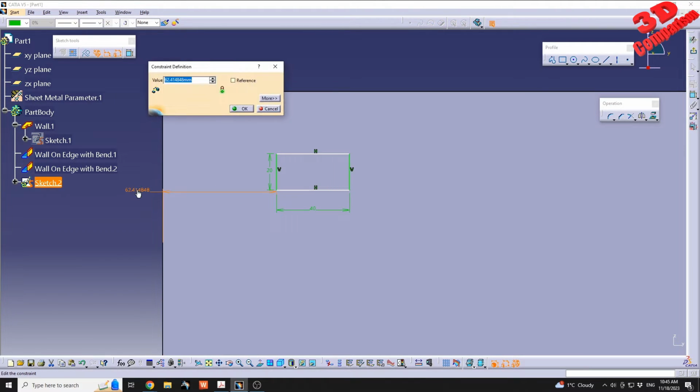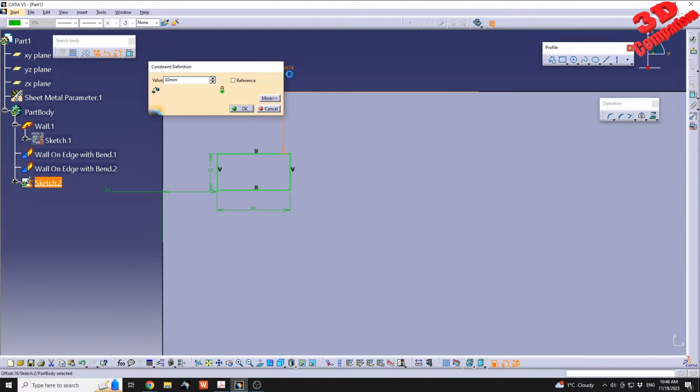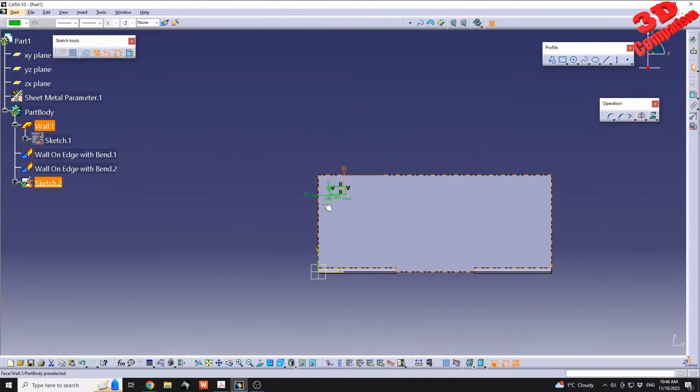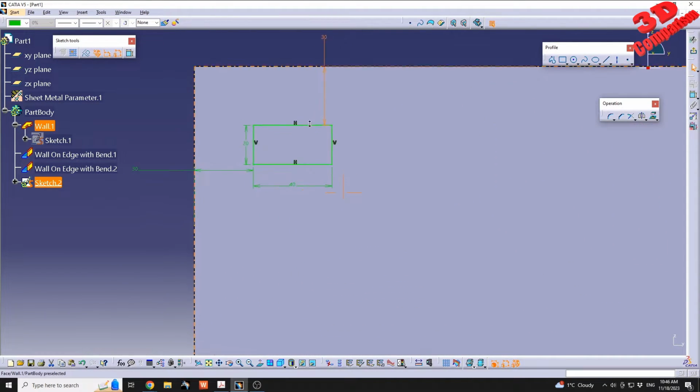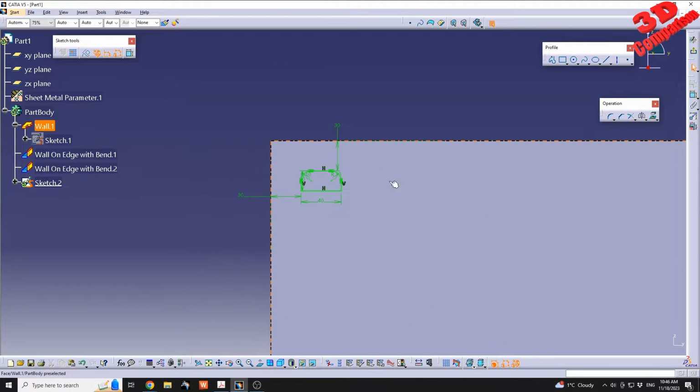If you want to, we can also have this constrained. So all the way up to this side, I will constrain this to 30mm. And for the top, I will have this constrained again to 30mm. So this will be that profile for the louver, but it is highly recommended that we add a radius on the top to have that louver defined. Therefore, I will go over here to corner. I will do a rectangle selection to grab both vertices at the top. And now I can press tab. That will take me within sketch tools. I will type in 10, and we're gonna have those two added.